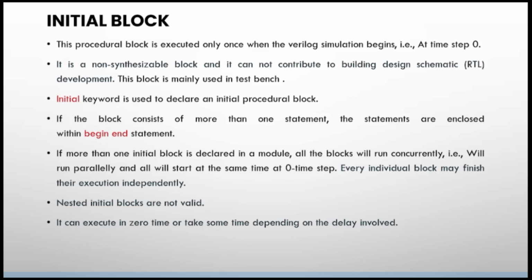Also, in your Verilog code, you can have many initial blocks. There is no rule that you should only write one initial block within your particular code. You can write any number of initial blocks, and while you are running the code, all these initial blocks will be running parallelly. That means everything will be started at zero simulation time. So if you are taking 10 initial blocks, all these 10 initial blocks will be starting at zero time unit.